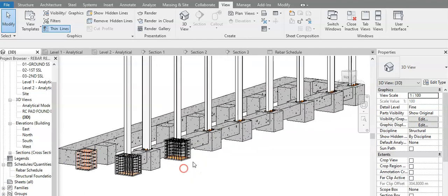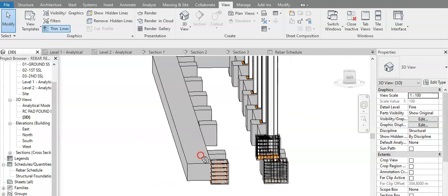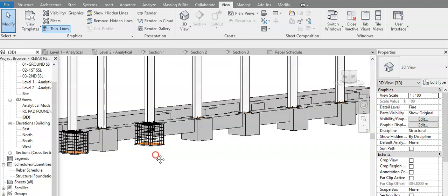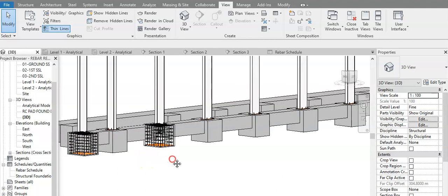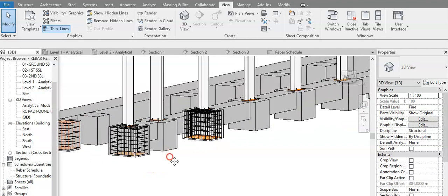With regard to the concrete, what concrete we use here is all specified by the structural engineer, whether it's C25, C30, C35, and what I mean by C35 or C20 is the compressive strength it will reach in 28 days for that specific concrete.